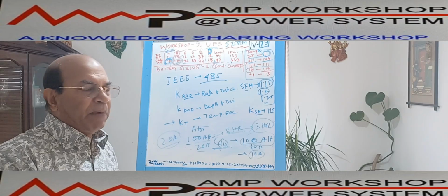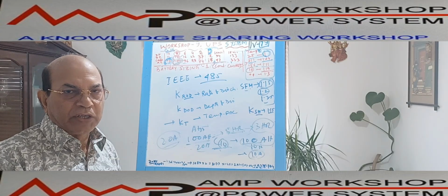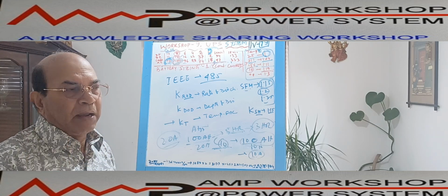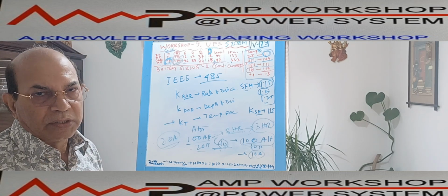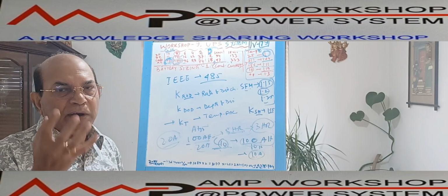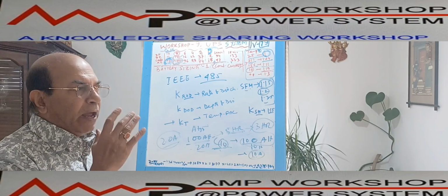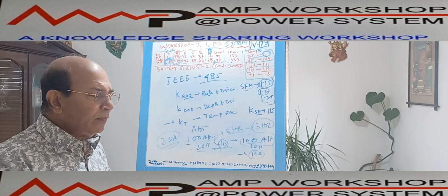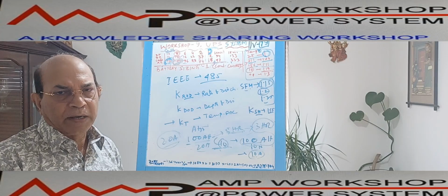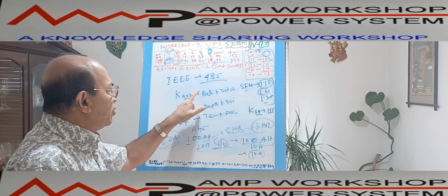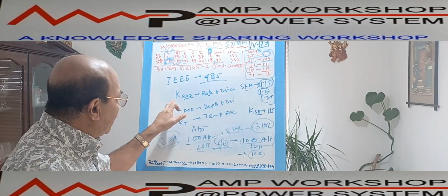For a particular battery which is rated for 8 hours or 10 hours, if we discharge it over another period of time like 6 hours, 4 hours, 2 hours, 1 hour, 30 minutes, 15 minutes, how much current and how much ampere hour it can deliver, the manufacturer provides a curve or a tabular form. From the tabular form or from the curve, we can calculate a factor which is called the rate of discharge factor. So that is the important thing.